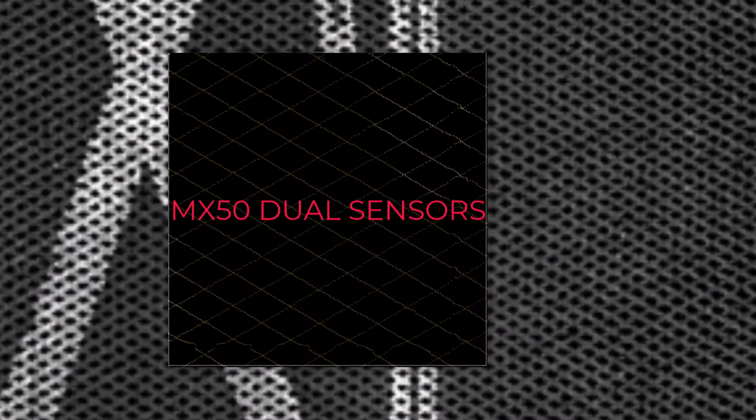So we're looking at a sample of a point cloud data set from an MX50 where I've just gone in and taken a square meter section of my data, and within this square meter we traveled at about 35 to 40 miles an hour with the scan rate of 1 megahertz. You can see the butterfly pattern here that was captured with the MX50, and within this 1 square meter section we've got approximately 4,000 points.